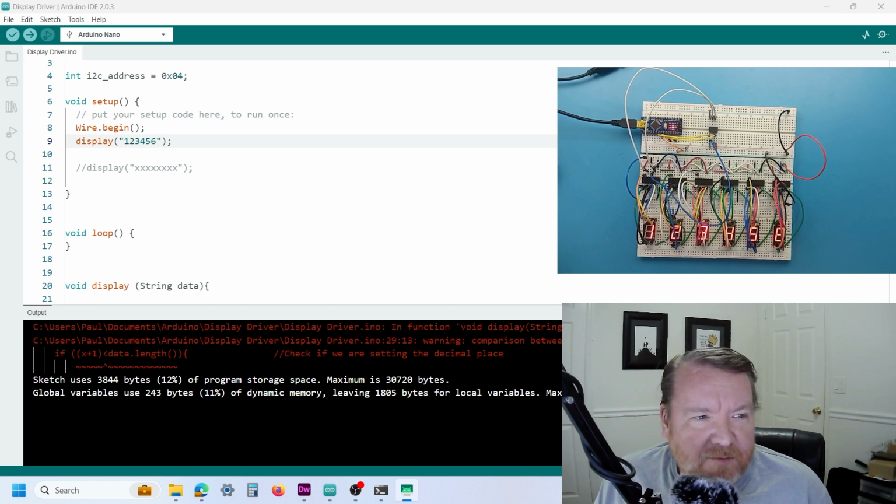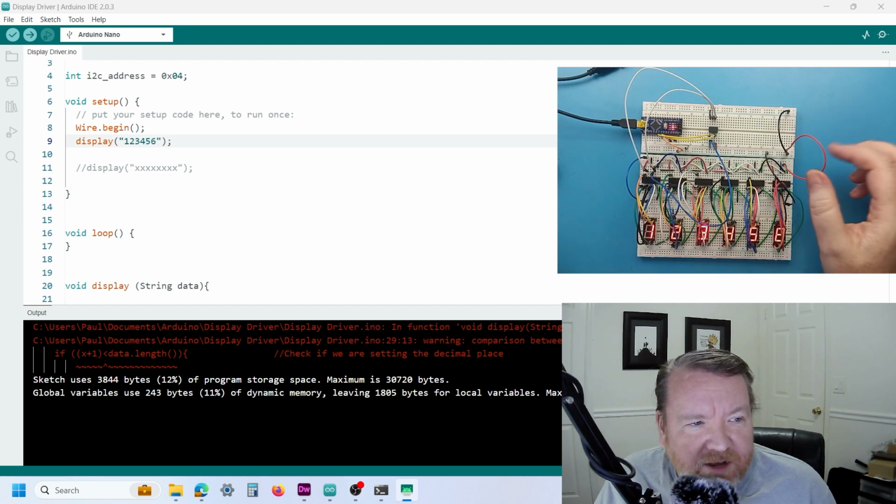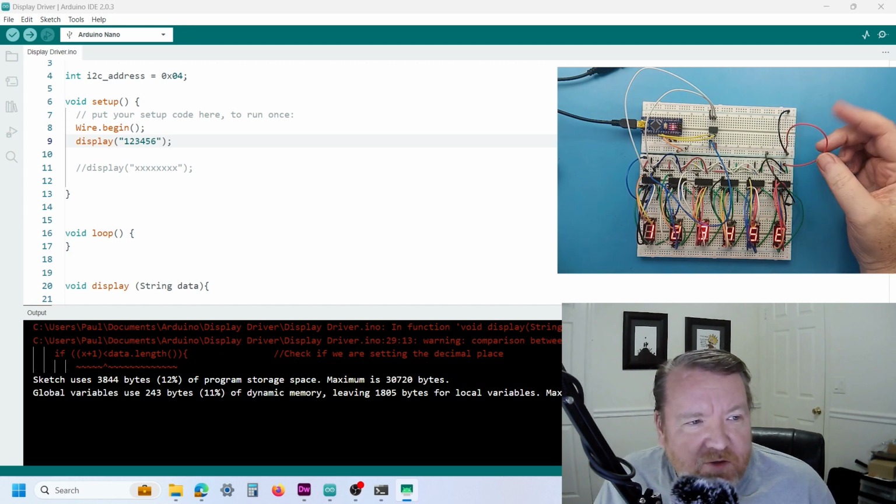Okay, so I'm back again now. We were having trouble trying to figure out why the data wasn't being displayed correctly on the 7-segment displays. Finally figured it out. It was just a small case of I'd not connected the power to the chip.